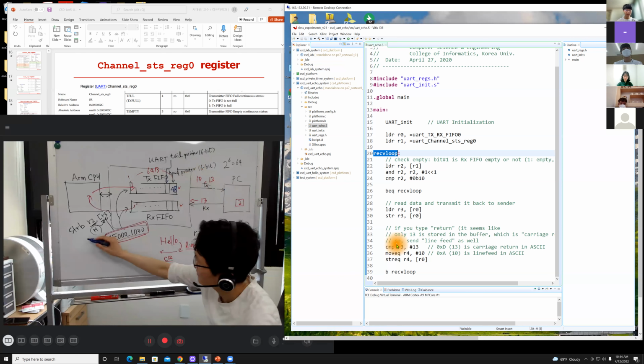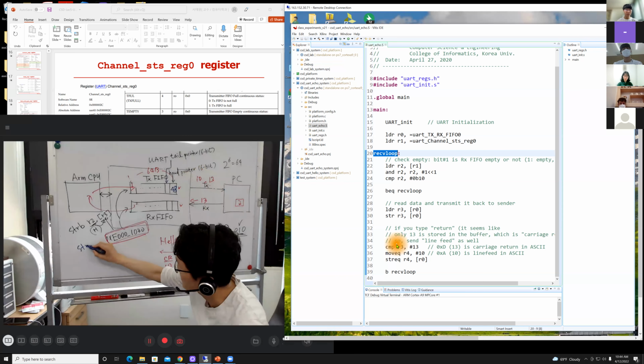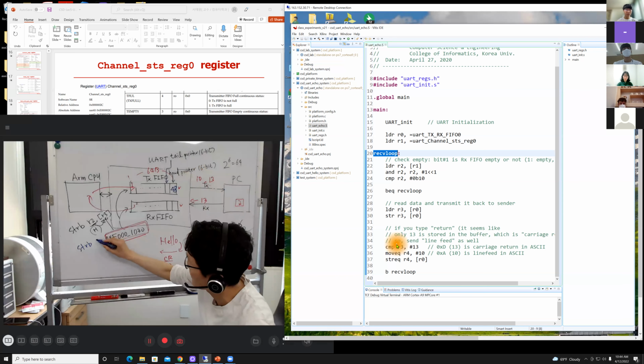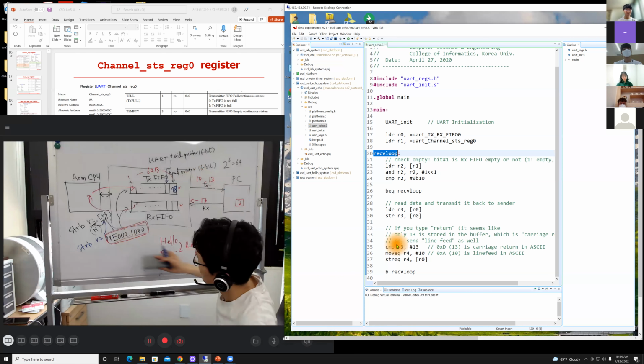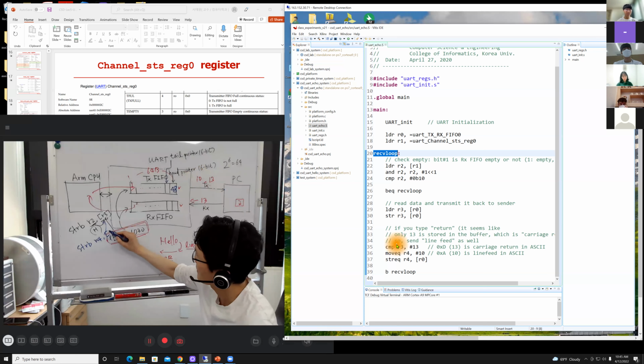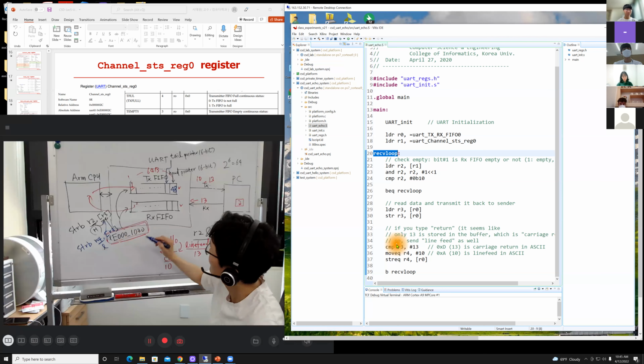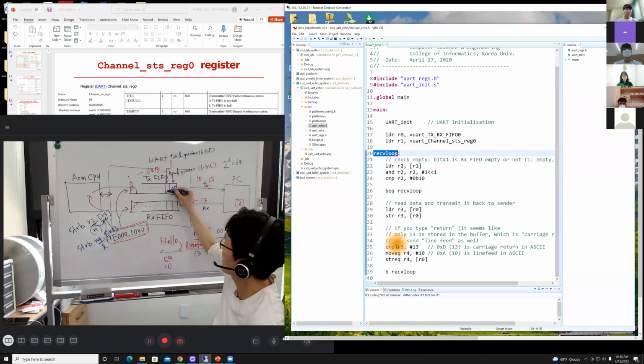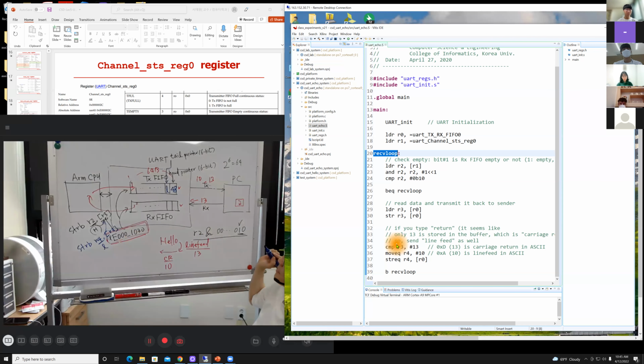And you write the next instruction, store byte, same R2, same instruction, but R2 contains R4, okay, R4 and R3. So let's say R4 contains L, okay, then L, whatever it is, L will be written to the location where the tail pointer is pointing.